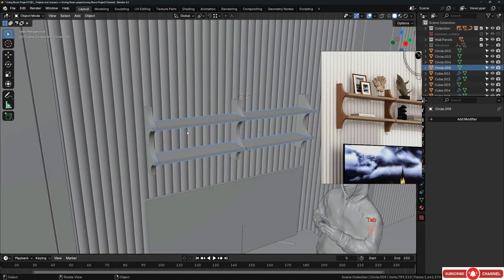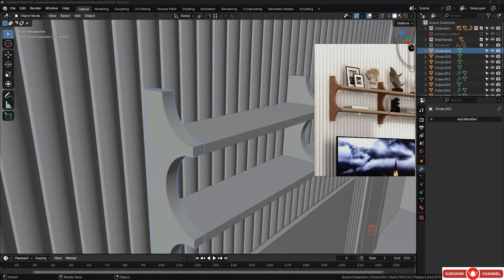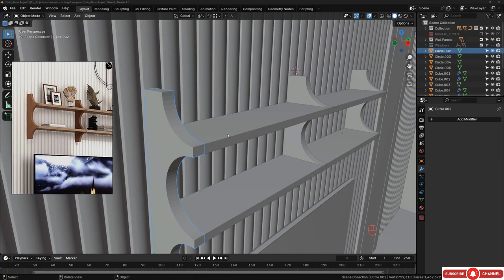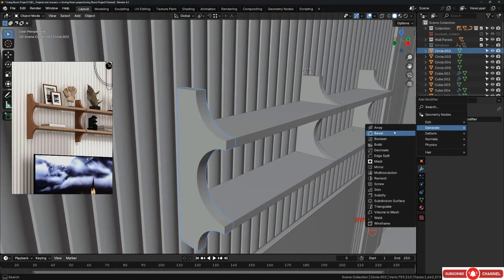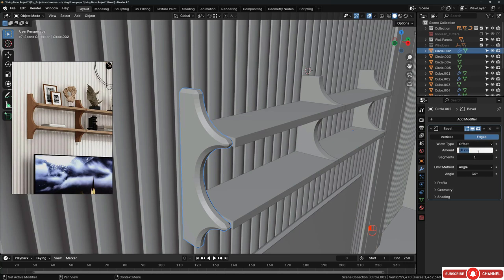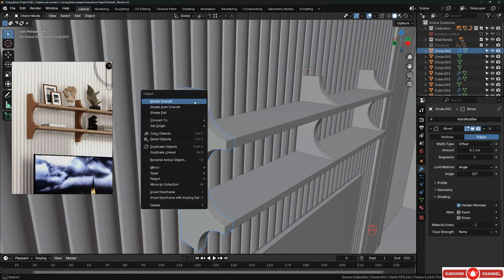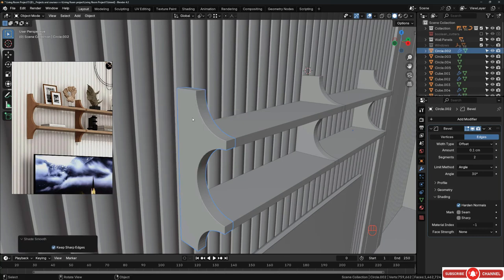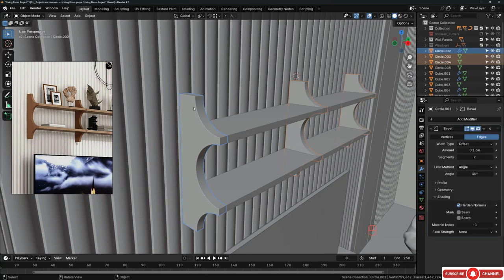After that, now you can give it a bevel. So let's start with these. All right, let's move this over here, and let's go to the modifier, Shift A, and let's add bevel. Let's add 0.1 centimeter with 2 segments maybe. Harden normal. Grab this piece, right click, shade smooth. And now I will grab those together, hold Shift to grab this piece as the last thing to select, and then hit Ctrl J to merge it with this one.